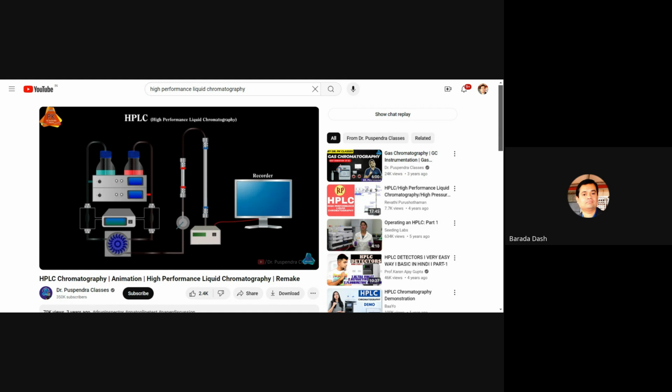Now let us discuss the working of these HPLC instrument. First, we will start the HPLC instrument. Then all parameters will be entered by the help of available HPLC software. And these parameters are solvent ratio, flow rate, runtime, type of elution, etc.